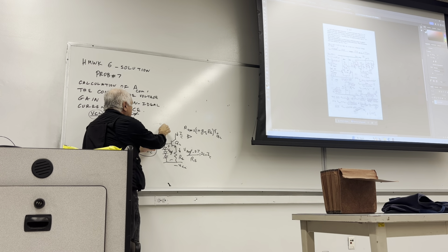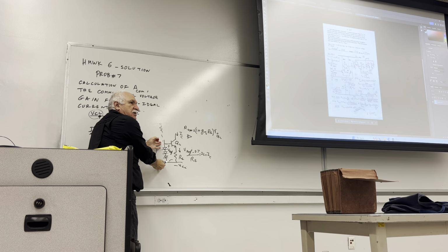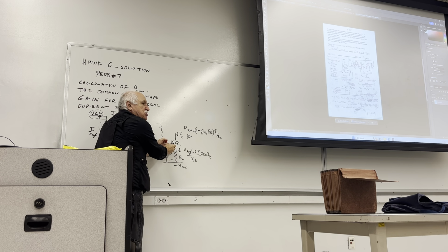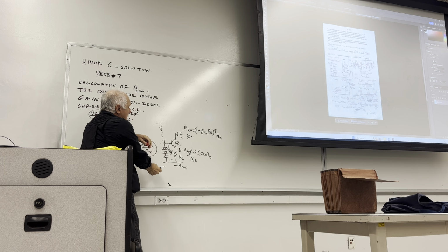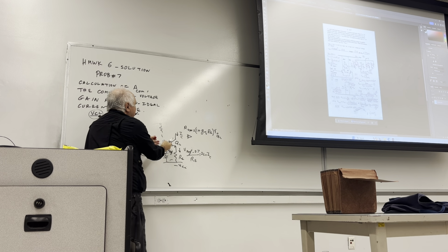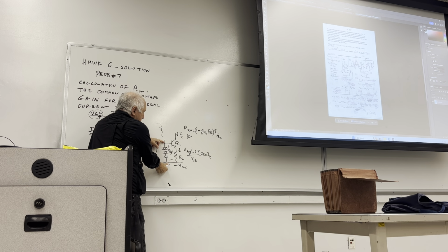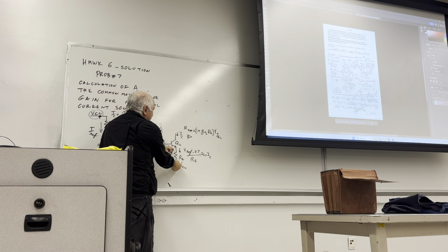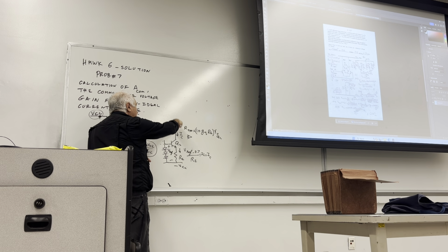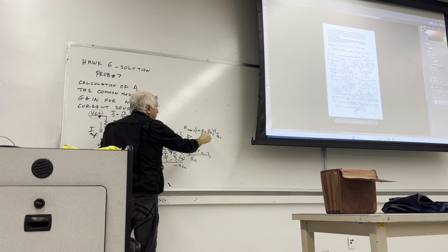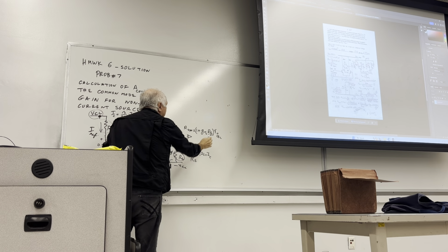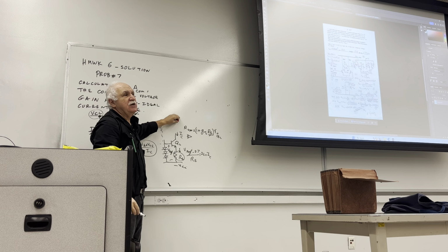It could be a resistor with a Zener diode in here, biasing the Zener. Zener biases this, which is the reference, or a few diodes put together. You can create a voltage difference between the 2 points, and therefore on the Re, therefore a current in the Re, which is the current in the IC. But because of this Re, we will get a gigantic improvement on the dynamic resistance.